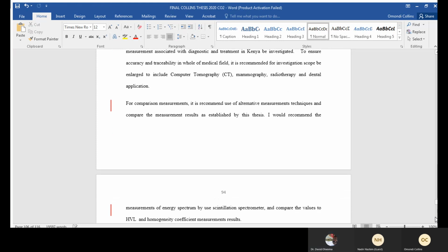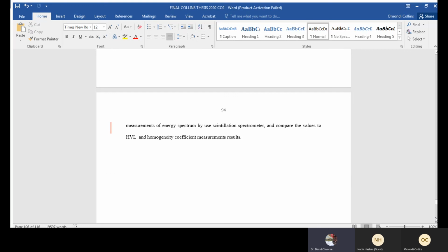So you finished? Yes, I finished this. Yes, so one last thing you should also point out very clearly, the issue of records. Ideally, records should be kept of each survey performed, and this should include the owner of the instrument, manufacturer's name, model number, serial number. Of course, signatures of the individuals who performed the calibration, date of calibration, and the next expected calibration date. All such records of calibration results should be kept for some period, maybe 3 years, or depending on your organization, let's say the Bureau, or you can recommend for the Nuclear Regulatory Authority how long.